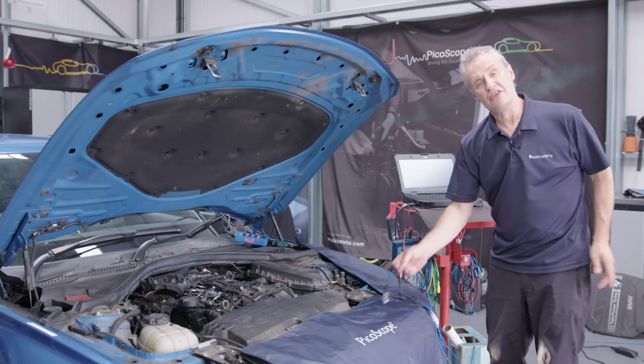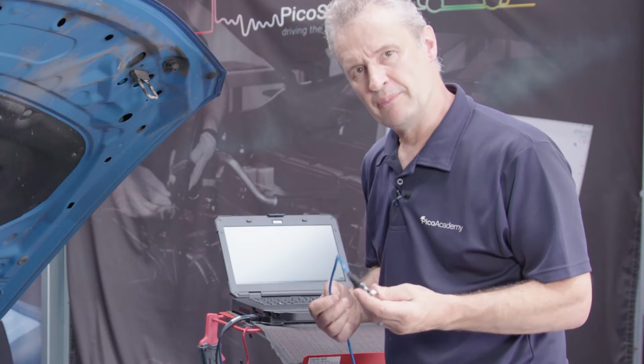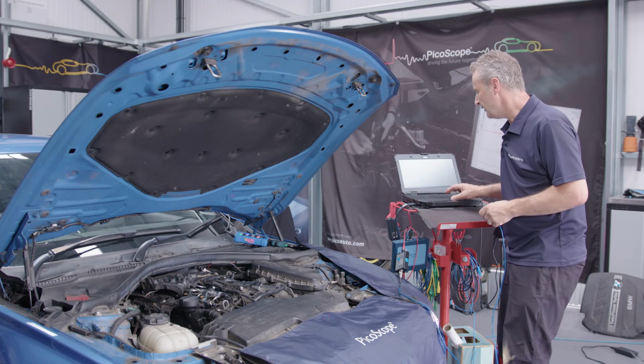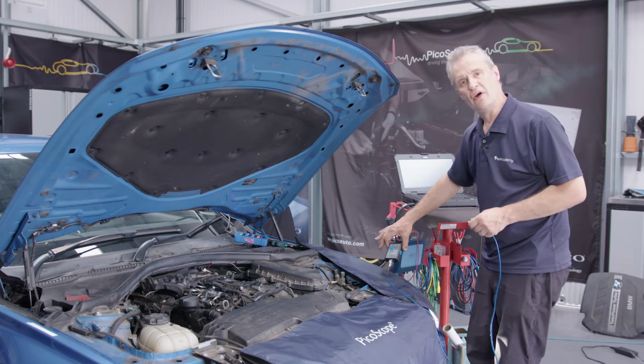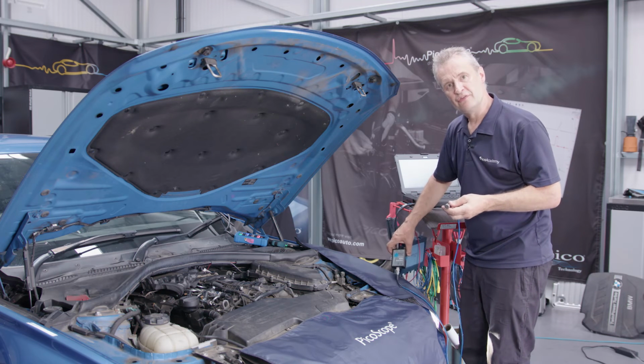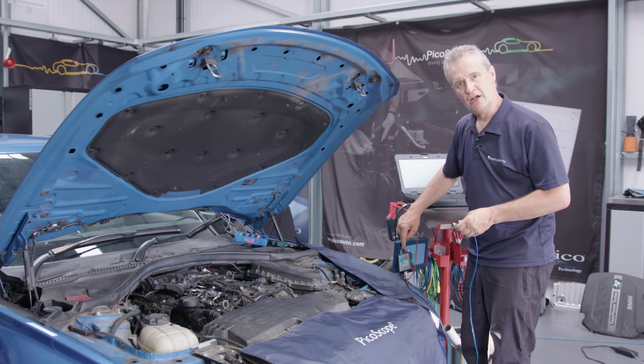Alright, so we're now going to describe a new setup that's using the accelerometer as a contact microphone. So it's a little bit of a cheat, in fact. We go into the software and we say we've connected a TA259, but we claim that the accelerometer that we fitted is in fact a microphone. It only requires one input, so it's channel B only.